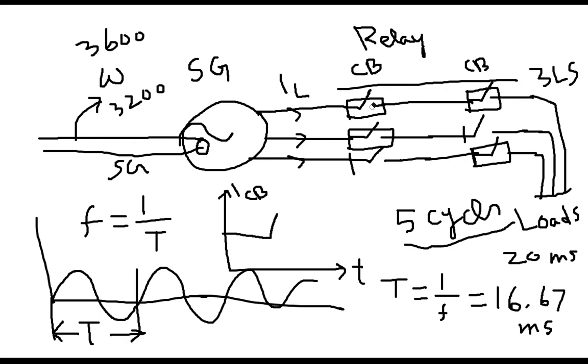So what will you do? Will you keep them always open in that way? No. You should reconnect again because now there is no fault and no disturbance is going on. If you don't connect back, then customers will be impacted. So you have to connect them again. That reconnecting time, after it was opened, is after this time, 30 cycles to 60 cycles.